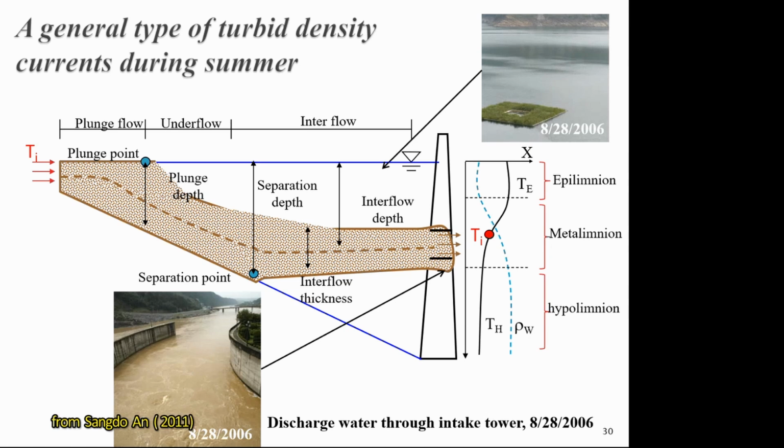so there's no problem anywhere else in the river downstream. But because they placed the water intake here, and you get the density current passing straight through it, you just capture your density current and you just flush it downstream. That is exactly what's happening at this site. What can you do about it? Huh? So this is the question. That's what's coming out. Sang-Do did a PhD with me on this problem.